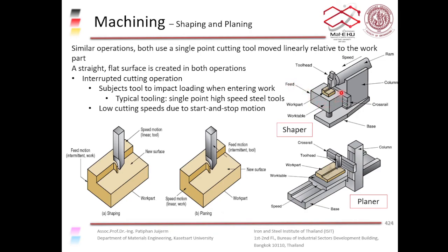Okay, so the head will move from back to front, cutting a new surface, and when the head moves back, it will feed the workpiece one step, and the head will move forward again, cutting the surface, and then move back. Okay, so you can see that it is a non-continuous cutting process, so it is quite slow because you have the start-stop process, cutting and then stop cutting and then cutting again.